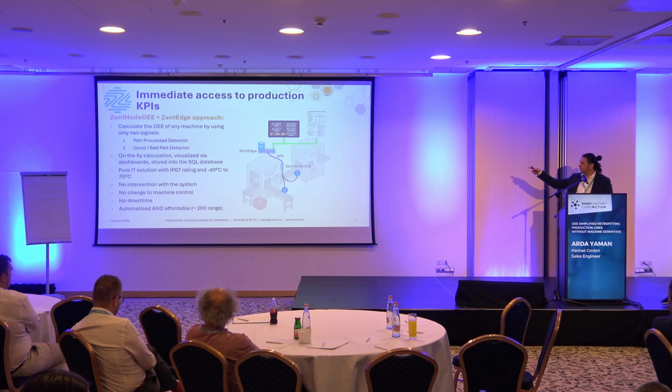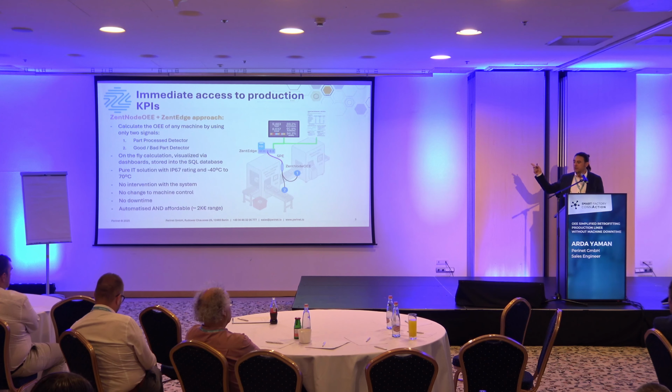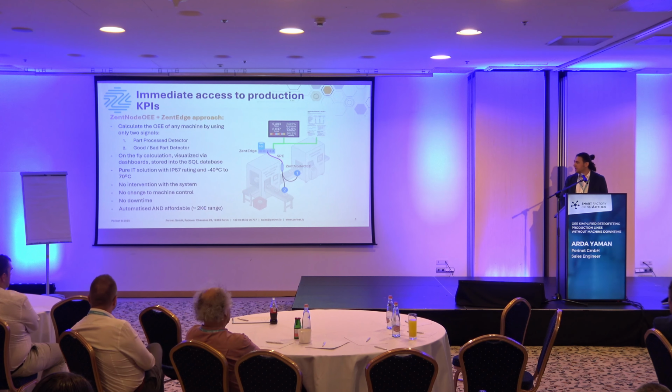We take this data, put it in ZendNode OEE, calculate everything right at the edge, and push the calculated OEE data into an edge computer called ZendEdge in this case. In the ZendEdge, there is an SQL database which is tailor-made for this specific solution. All the data is stored in that SQL database and then pushed directly to your IT network, so that you can use it in any type of system you might use: your ERP system, your CRM, your MES system.